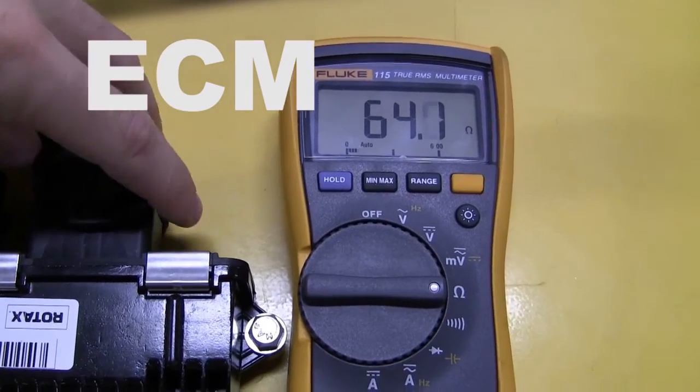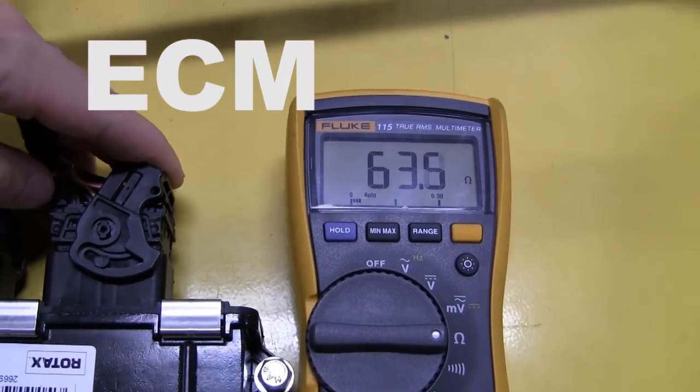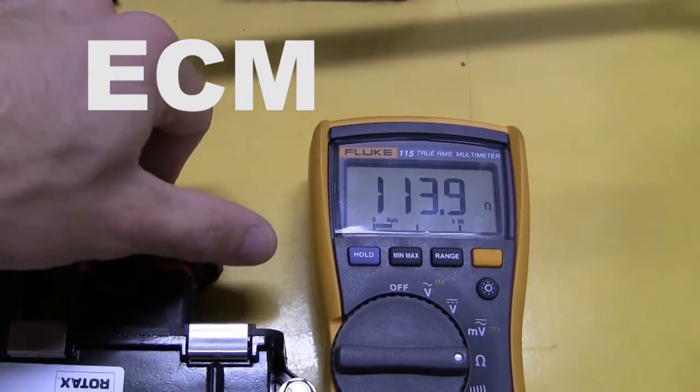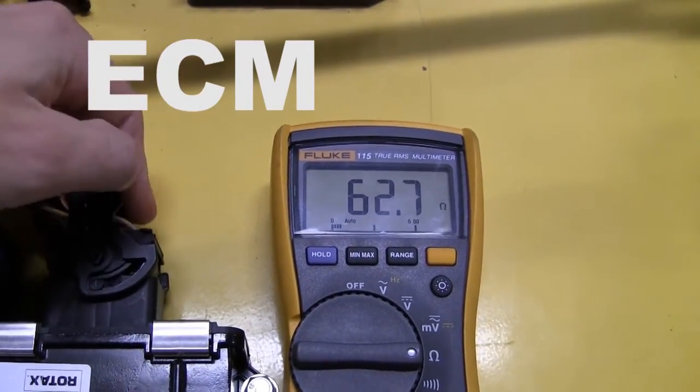In this video, note how the resistance changes when unplugging a module with a terminating resistance and unplugging a module without a terminating resistance.